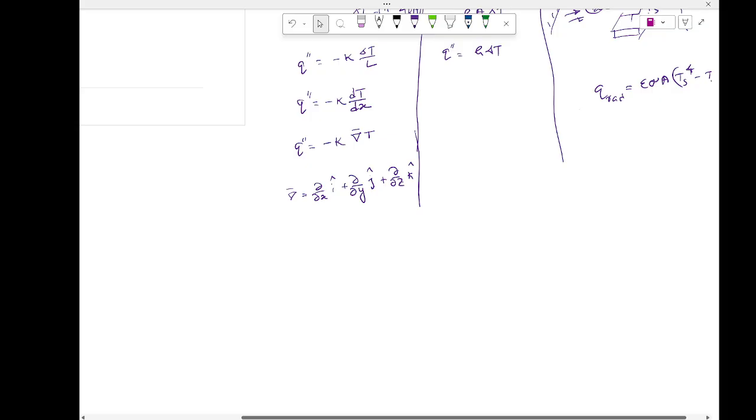So this surface, whatever it can see around, as I was saying, if it sees the ceiling, it is going to give it heat. If it sees the sidewall, it will give it heat. If it can't see the floor, it will not give it heat. Does that make sense? Everyone understand? So that's the concept of radiation, okay?